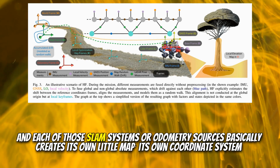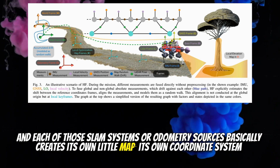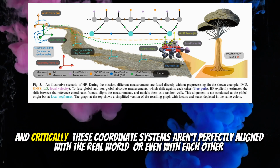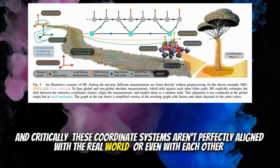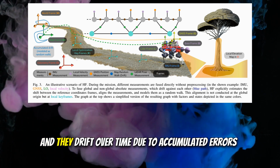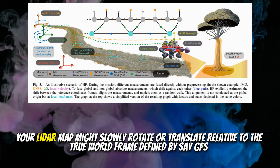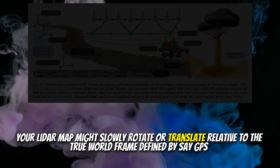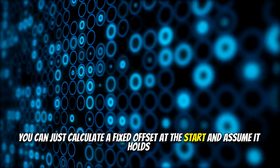And each of those SLAM systems, or odometry sources, basically creates its own little map, its own coordinate system. And critically, these coordinate systems aren't perfectly aligned with the real world or even with each other. And they drift over time due to accumulated errors. That's the killer. Your LiDAR map might slowly rotate or translate relative to the true world frame defined by, say, GPS. You can't just calculate a fixed offset at the start and assume it holds.